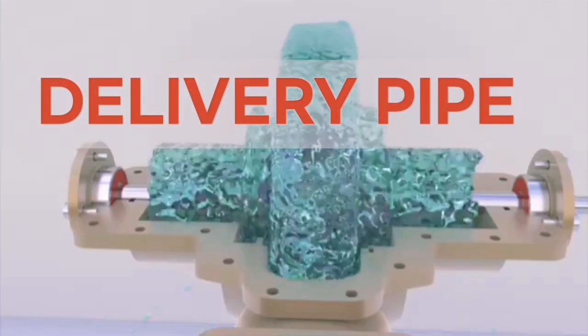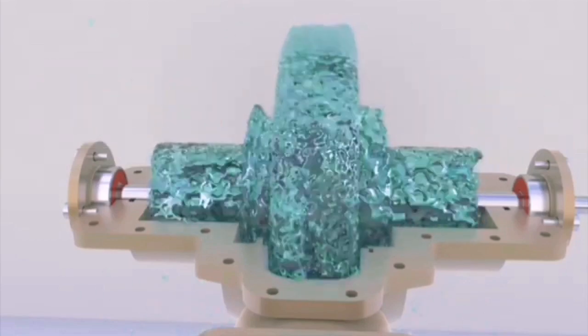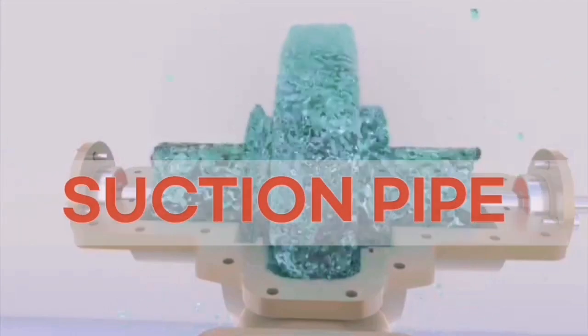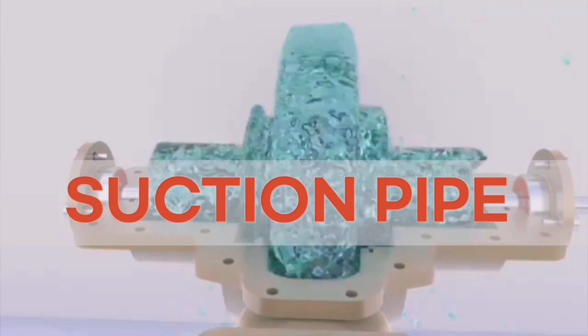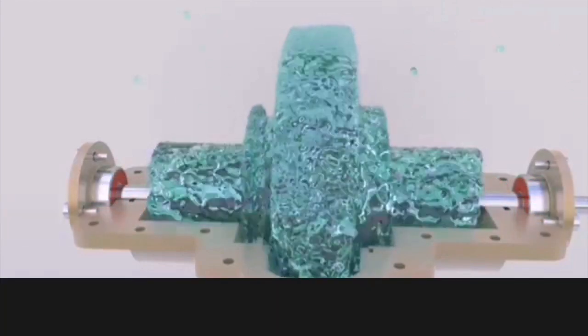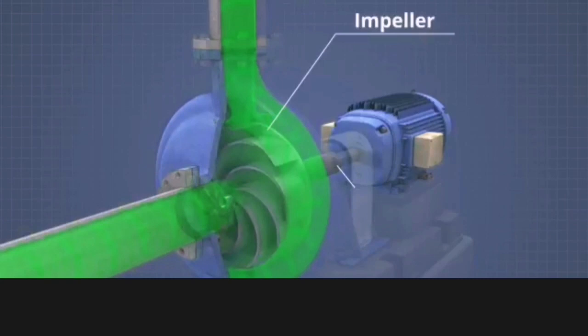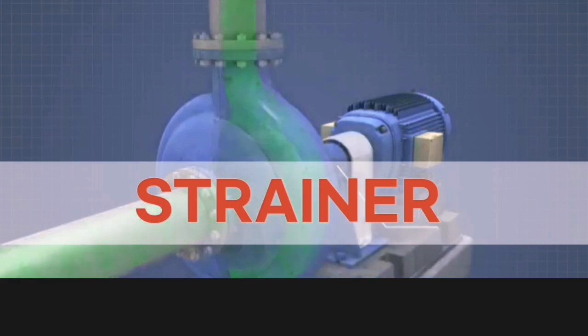A pipe whose one end is connected to the outlet of the pump and the other end delivers water to a required height. Number 4, suction pipe. A pipe whose one end is connected to the inlet of the pump and the other end dips into water. Number 5, foot valve. It is a non-returning or one-way type valve fitted at the lower end of the suction pipe. Number 6, strainer. It is used to prevent foreign particles from entering the suction pipe.